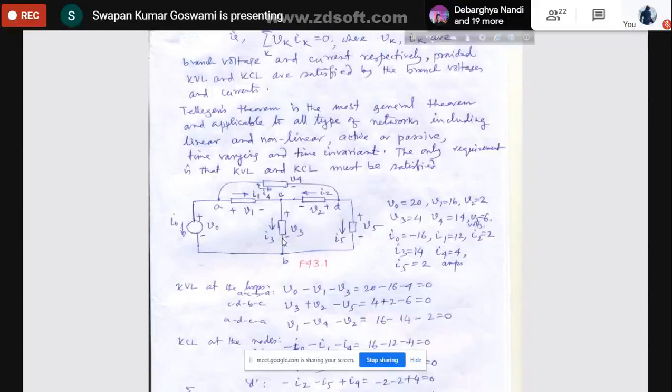Okay, generated power will be equal to the load power plus loss of power. If there are other connecting wires, there the power loss will take place, so those are also to be included. If you include everything, then you will always see that the sum of instantaneous power in the circuit, including sources and loads, everything will always be equal to 0.